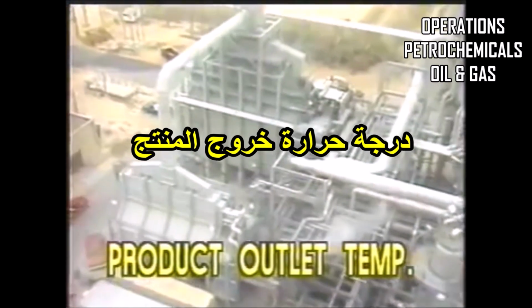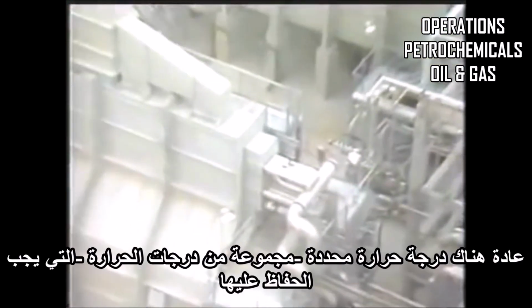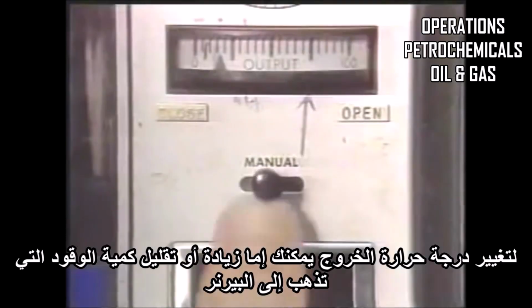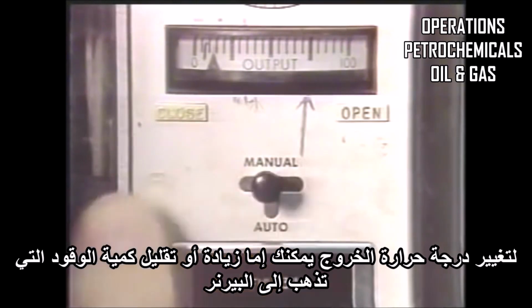Product outlet temperature is the temperature of the process flow as it leaves the furnace. Normally, there is a set temperature or range of temperatures that must be maintained. To change the outlet temperature, you either increase or decrease the amount of fuel going to the burners. When you adjust the fuel rate, however, you must also change the amount of air going to the burners to ensure safe and complete combustion.